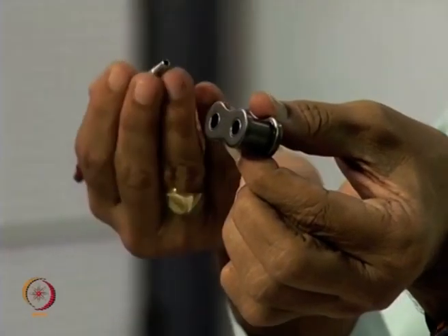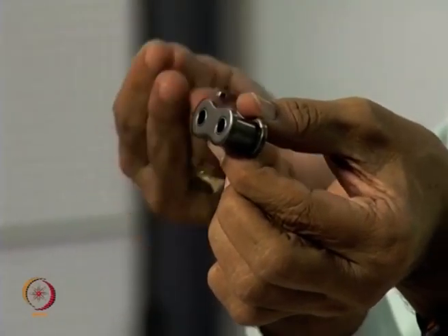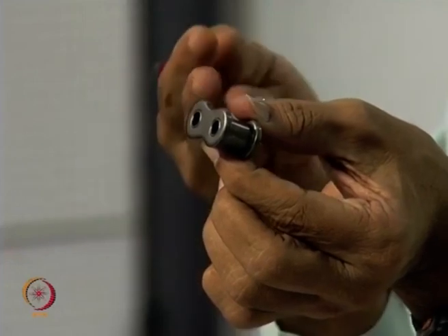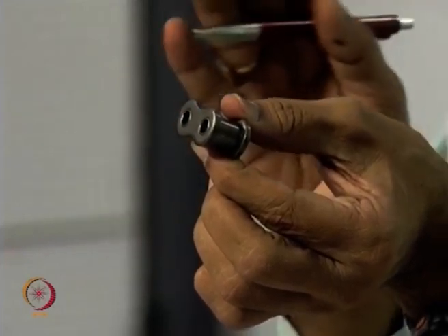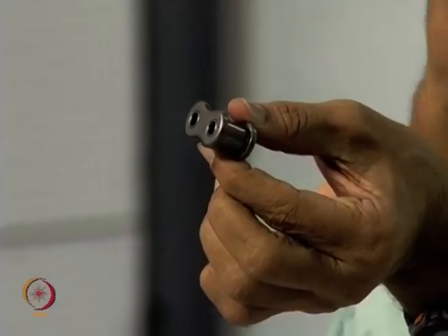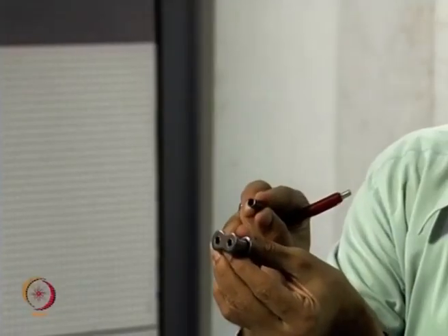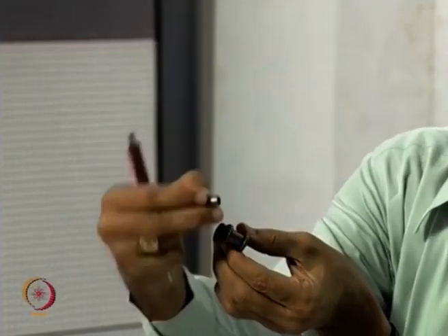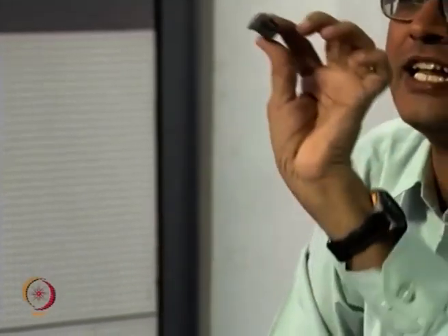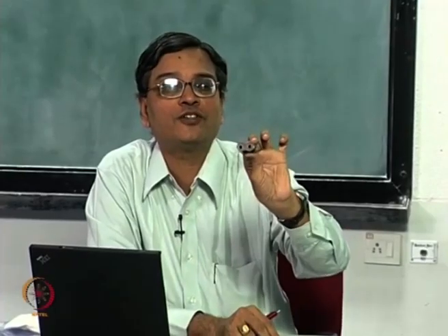Finite geometry I cannot approach by theory of elasticity. Definitely I can approach it by finite elements, absolutely no problem, but there I have to apply the boundary conditions. What I may not know from a production shop is that this may not be perfectly cylindrical; it will have a variation. So, suppose I do an experimental analysis directly on this component, which acts like a prototype, then I capture all the manufacturing variations that have gone into its fabrication.